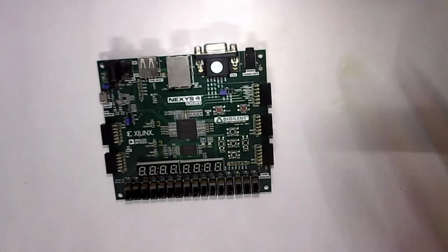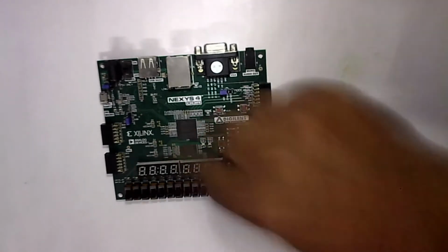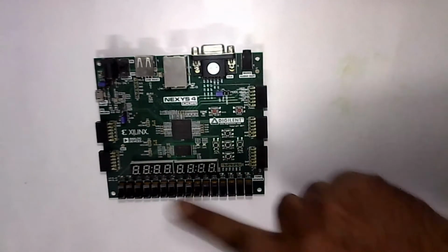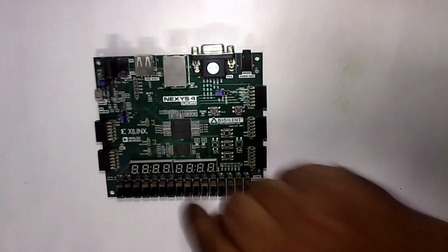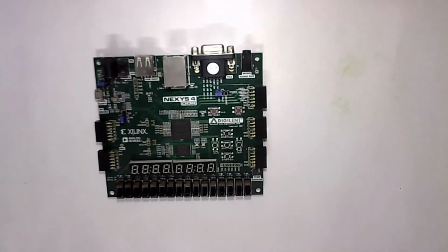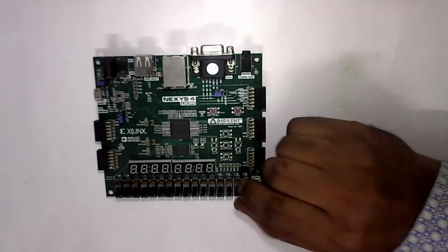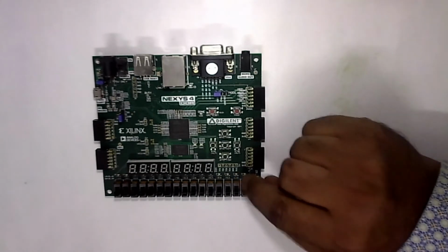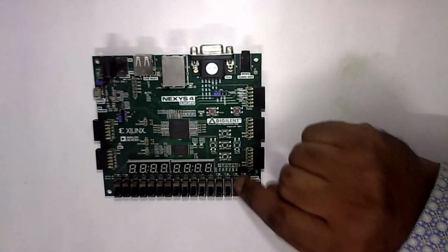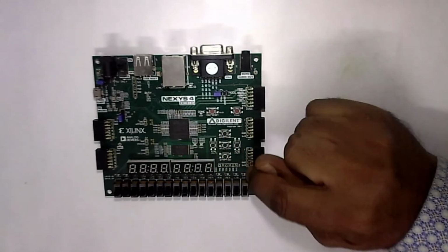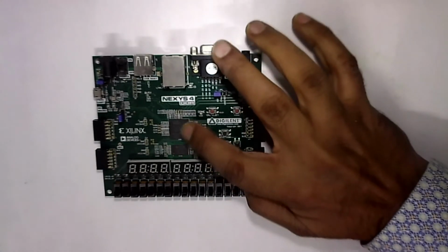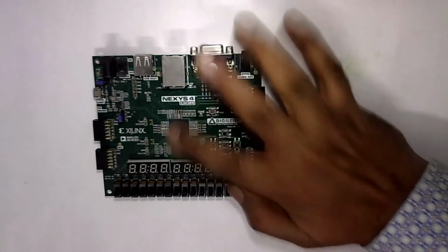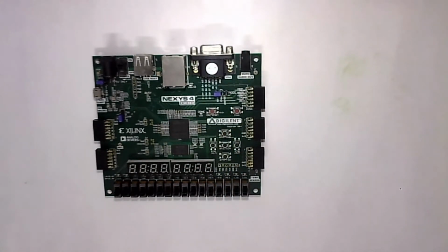So what is happening is the following. This is called the IO constraint. I am basically specifying which physical pin is connected to which logical pin. So for example, let's say an AND gate has A and B inputs, and Q is the output. I can use these two switches as the A and B inputs. They have a certain physical pin number that is mapped to the logical input of the AND gate, and then there is an LED here which again has a physical pin number that is mapped to the logical output of that AND gate. So this mapping is referred to as IO constraints.